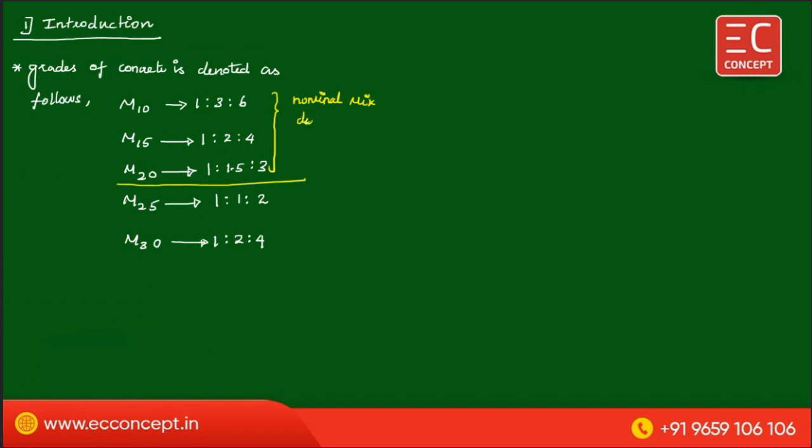For these two, or more than M25, we will use the mix design procedure as per IS code 10262. As per this code we will do the process.